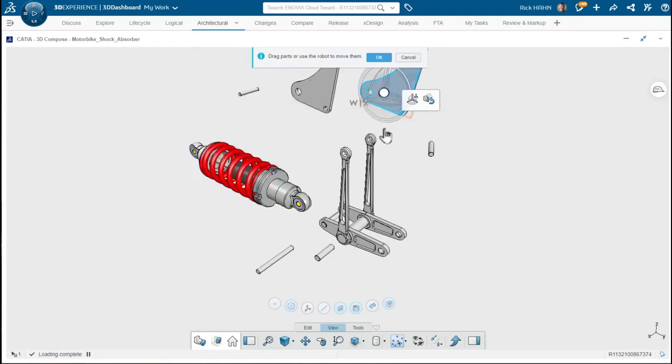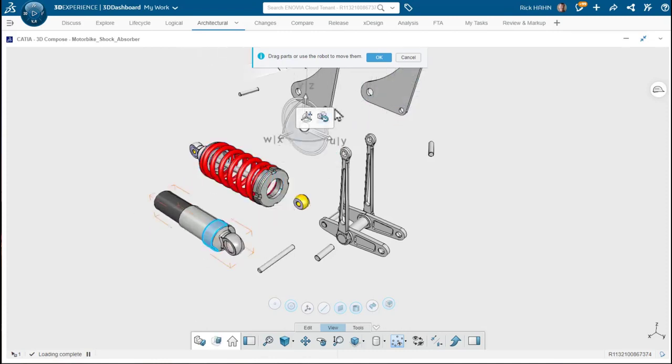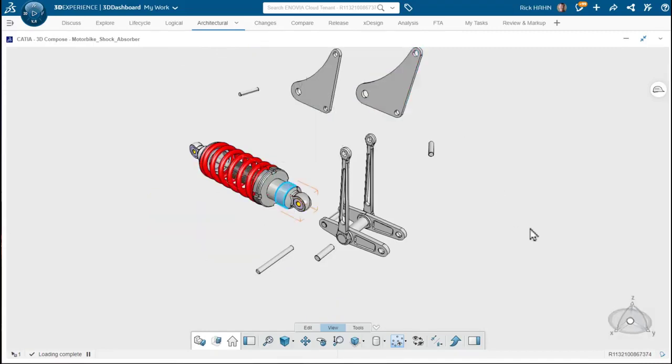But that doesn't necessarily mean that's the only thing we can move with that particular alignment. Whichever selection we make, we can then use that positioned local coordinate system to move that particular component that's in the selection. So the initial element really doesn't force us to relocate the coordinate system, just establishes its orientation.